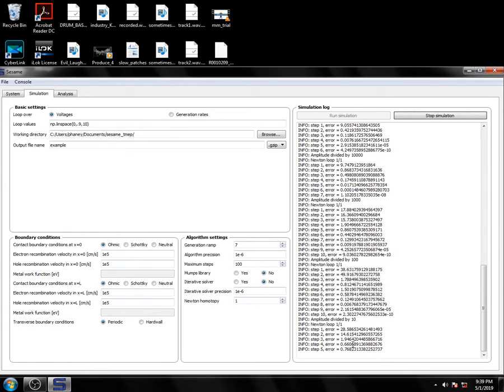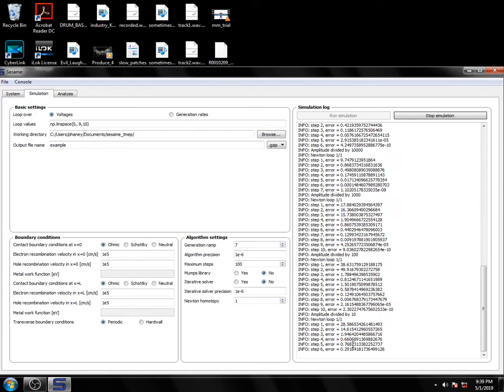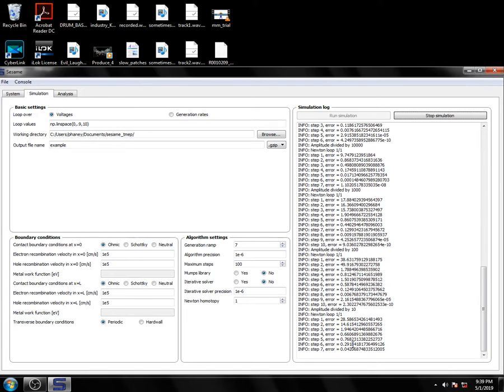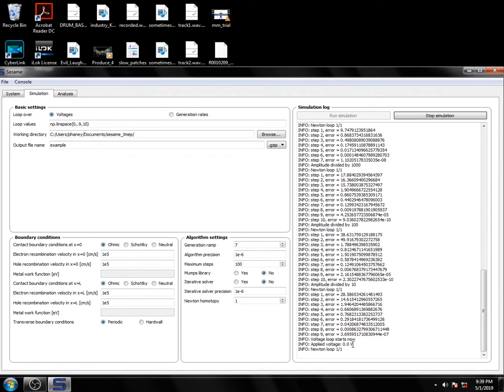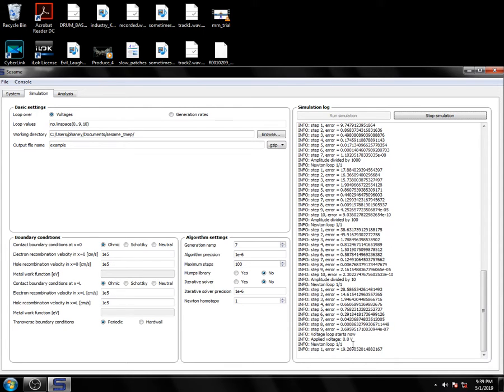In that case, the use of Sesame is much more effective if you use it in the context of a Python library. Because in that case, you can simply program massive parameter sweeps in Python scripts and send those to computing clusters, which can perform all the simulations simultaneously.